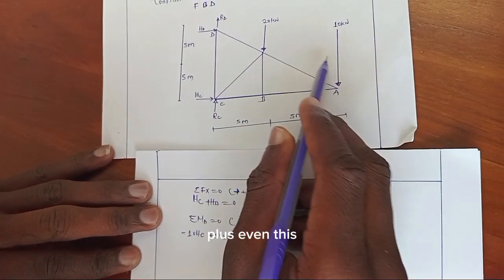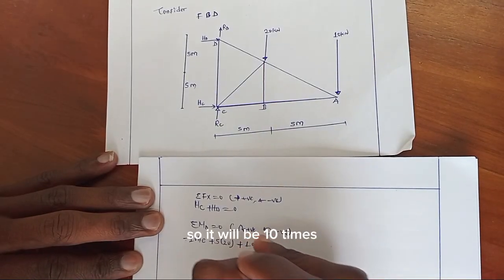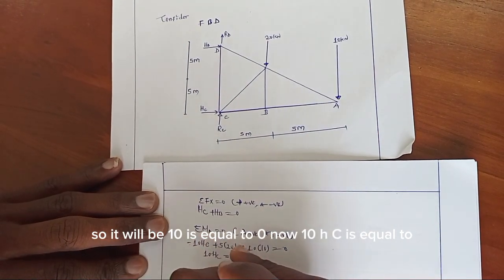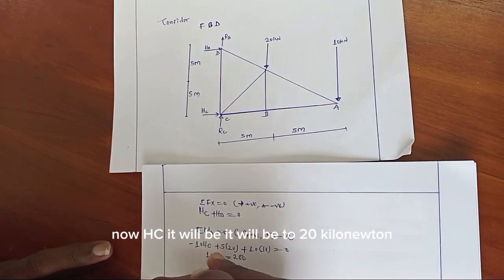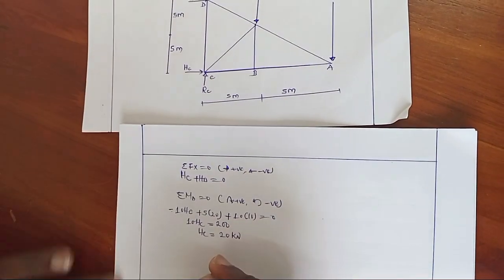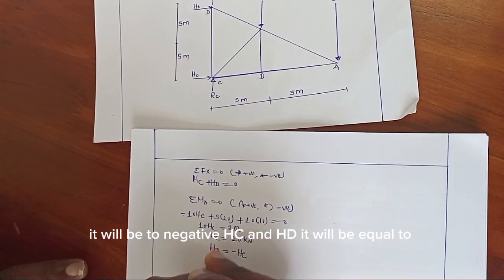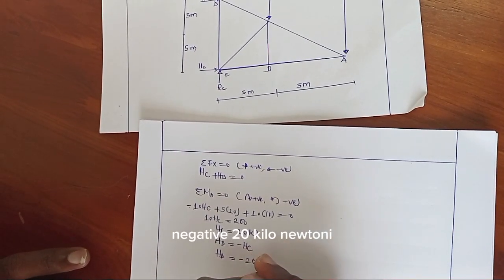plus this 10 kilonewton, it rotates clockwise direction towards point D, so it will be 10 times its perpendicular distance, which is 10, is equal to 0. Now 10 HC is equal to 200 kilonewton. Now HC will be equal to 20 kilonewton. Now in order to obtain HD, it will be equal to negative HC. Now HD will be equal to negative 20 kilonewton.